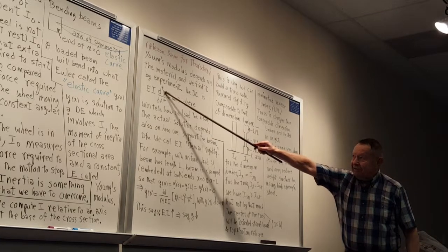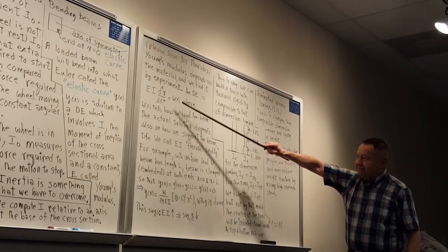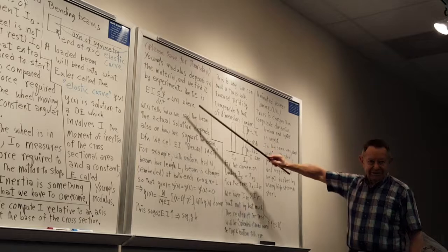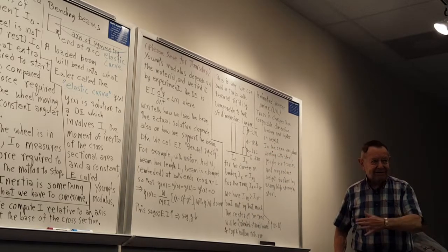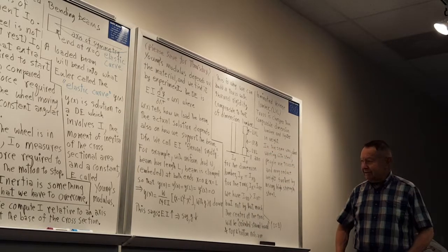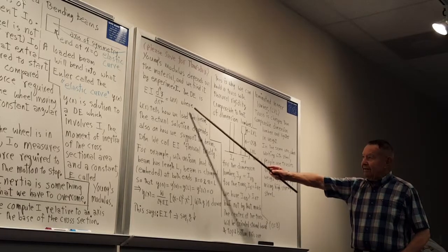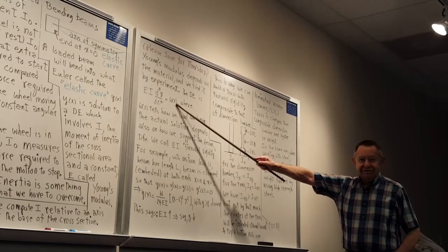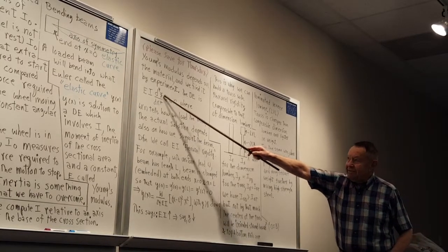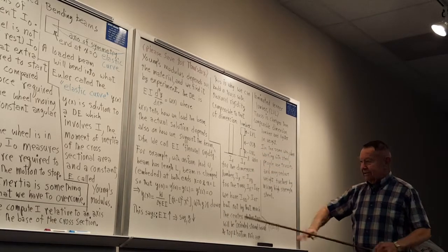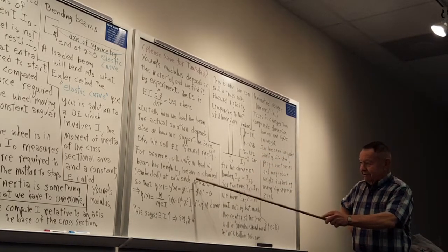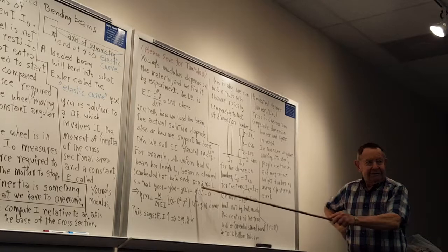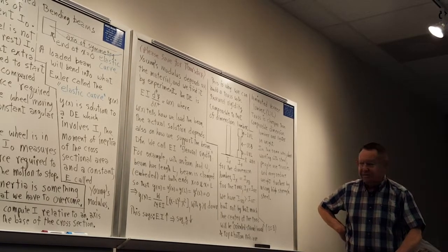The first time you integrate, you get the third derivative, and that'll be the integral of this, and so on. So you'll get a constant of integration each time. So there'll be 4 constants of integration by the time you get to y. So that means you have to consider your boundary conditions to get these constants.